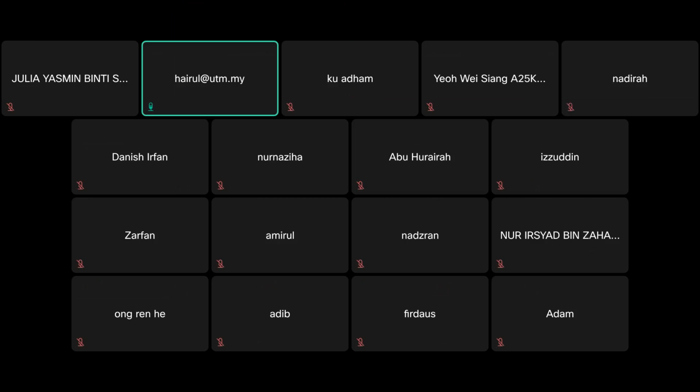Then for that assembly and exploded view, you have to do drawings. Then you also have to do a set of detailed drawings. So the complete set: the exploded assembly drawing, exploded view, plus the detailed drawing of each component, except the standard components. So that's what you have to do.